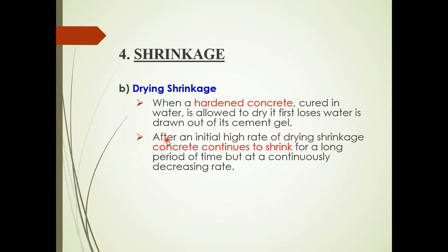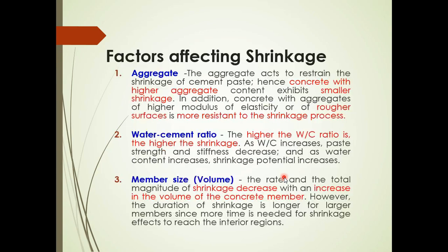Another one is drying shrinkage. When hardened concrete cured in water is allowed to dry, it first loses water that is drawn out of its cement gel. So after an initial high rate of drying shrinkage, concrete can continue to shrink for a long period of time, but at a continuously decreasing rate.